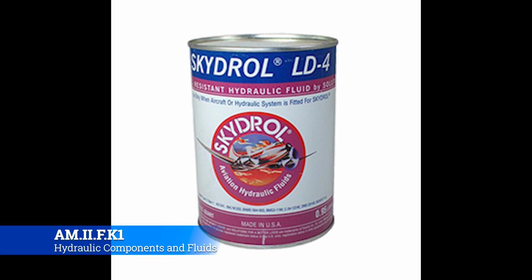So, Skydrol, by far, is probably the most common hydraulic fluid that you're going to come across. In your more simple airplanes, they generally will use push-pull tubes and cable systems. You won't see a whole lot of hydraulics. Once you start getting into the jets, that's when you'll start to see a lot more hydraulic implementation, simply because of the amount of force that the flight controls need to be able to deflect the air to cause a reaction in the airplane. So hydraulics gives you a way to put a little bit of effort in, but get a lot of output.